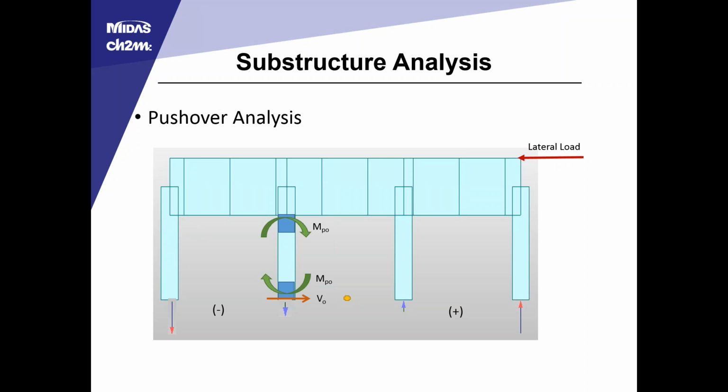In the second iteration, when we apply that first summed base shear as the lateral load and do a rigid overturning, we get equal and opposite reactions, certainly larger on the outside, just resulting about the center. That gives us different axial forces in each column, which will give us different ultimate moments, and then different shears. And as I said, we continue to iterate that until the lateral load and that sum of those shears are equal.